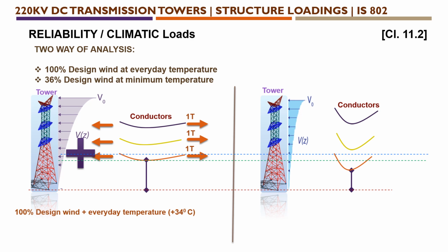So in order to reduce the sag, or in order to increase the ground clearance, we need to apply more tension compared to the left hand side. So for minus 5 degrees Celsius, we need to apply the pull on both the edges with more than 1.5 times the left hand side tension.